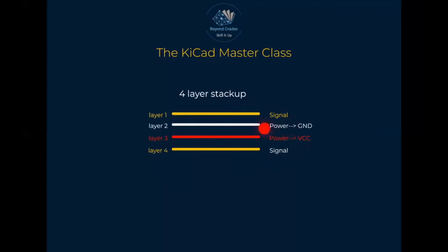When you learn how to work with a four-layer stackup, you're going to get spoiled, because you just draw a small line and a via, and boom, you've connected power. In like three or four vias, you have all your powers connected. So these are stackups that make some designers in the early stages get spoiled. They might seem complex, but once you start doing four-layer designs, you want to do four-layer for everything, and of course you're making your design much more expensive. So there are caveats when we go for four-layer designs. It's not something that you should be going for each and every day.